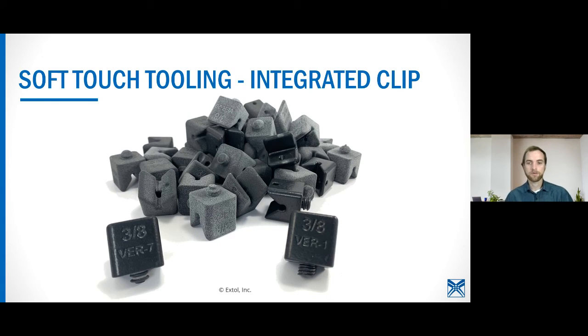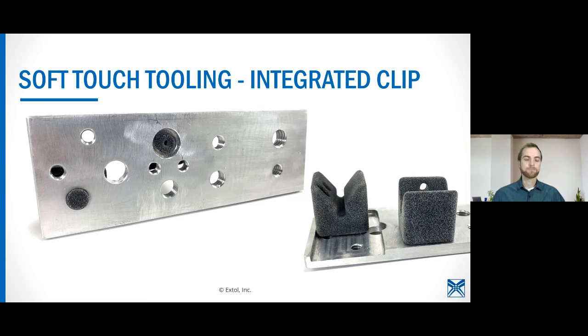So like I said, we're currently looking at different clip designs, specifically to attach to a machined base plate. This was prompted by a customer looking to combine traditional manufacturing capabilities in-house with the benefits of additively manufactured TPU. So you can see several iterations of the clip design here. Shown here, you've got a threaded one on the left as well as a snap fit feature on the right. And those are just a couple in a counterbore hole that have shown some promise.